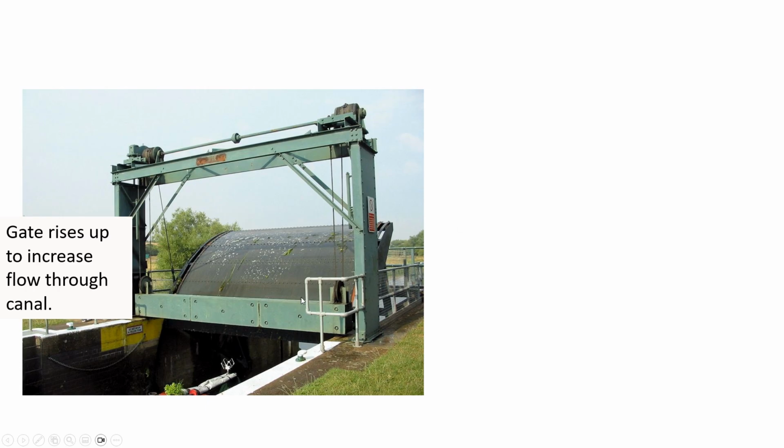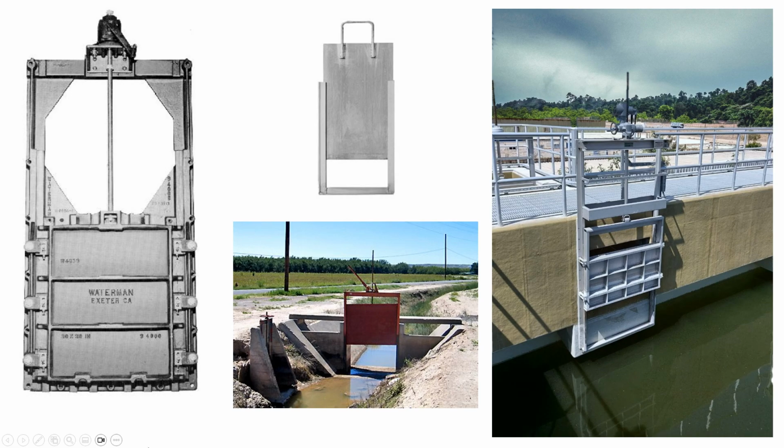There are gates like this which are designed to reduce the force required to lift the gate. And if we go back to these gates, you have to lift them partly because the metal plate itself is heavy, but also the pressure of the water on the gate is pressing it against the frame. And so there's going to be a lot of friction lifting it up because the hydrostatic force is acting over some area, and so there's a force inward on the gate that makes it difficult to raise as well.